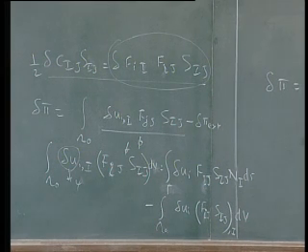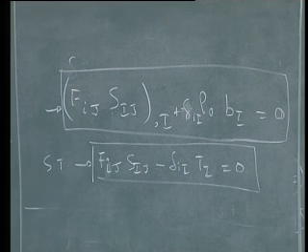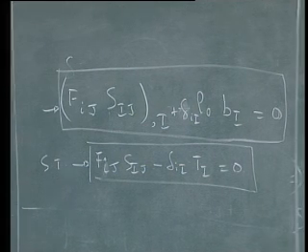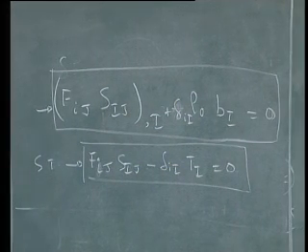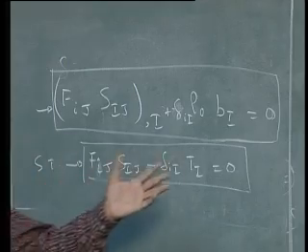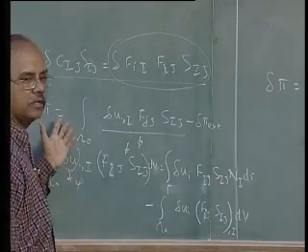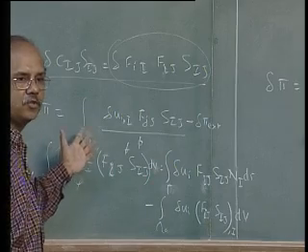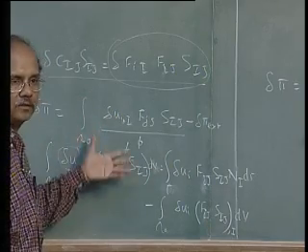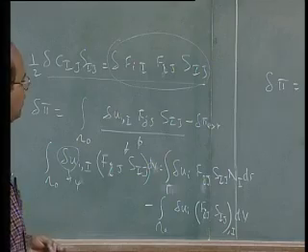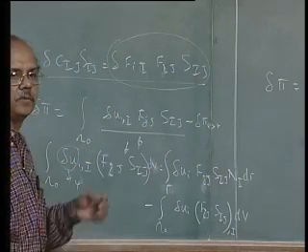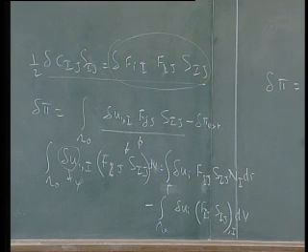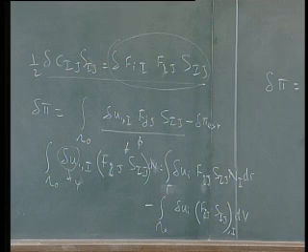Now, though we have derived this, this is not of much importance for us, because we will go back to the first step. Okay, remember that the first step is the potential energy theorem, and the second step, where we said delta phi is equal to 0 term. Delta phi is equal to 0 is actually our virtual work type of principle. So we will start from there, and the procedure is exactly the same as we did before. But the only thing is that in our B matrix there are additional terms like F's, and hence our B matrix would all be different.